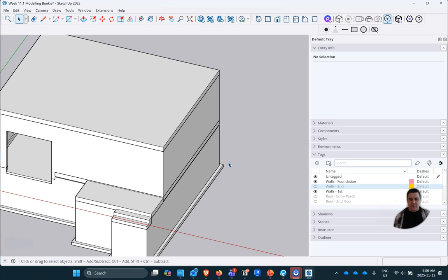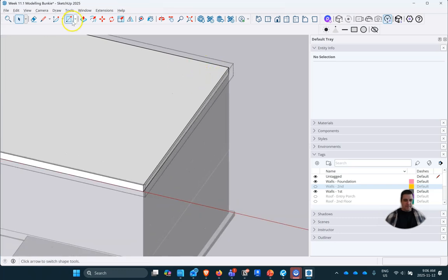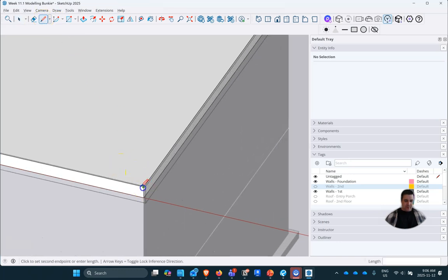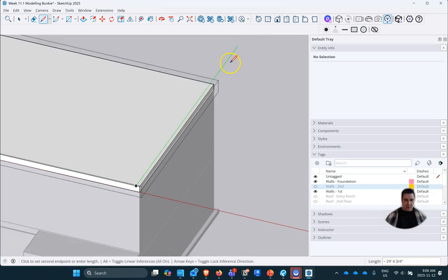And so we want to start off by actually editing this floor because we've got to build a hole into this floor. And so the first thing I'm going to do is offset a line here by 5.5 inches because that's our stud size. And let's put this line all the way across here. And that did not go very well. Put that line across there. Because I know that wall, we don't want to cut out that wall area. We want that wall to still be there.